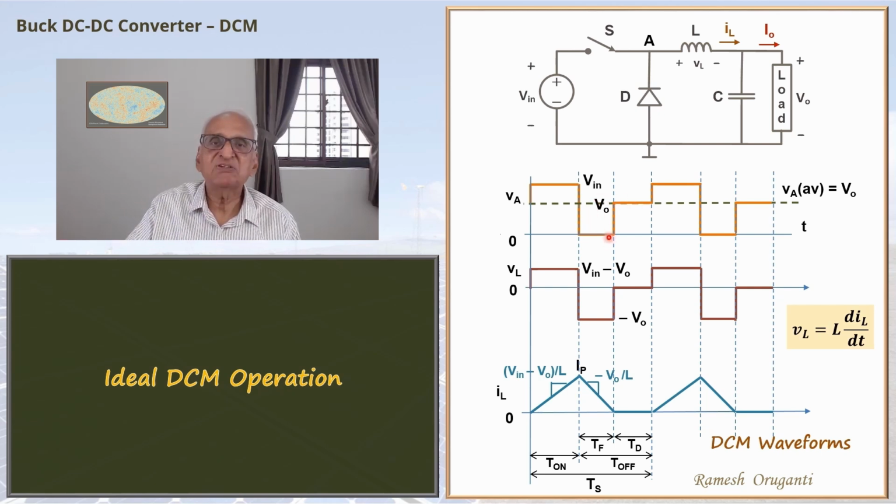The average of the inductor current flows through the load. The DC current cannot flow through the capacitor. The remaining part of the current, or the ripple current of the inductor current, flows through the capacitor. Almost all of the ripple current will flow through the capacitor. The capacitor will absorb it while producing very little ripple voltage.